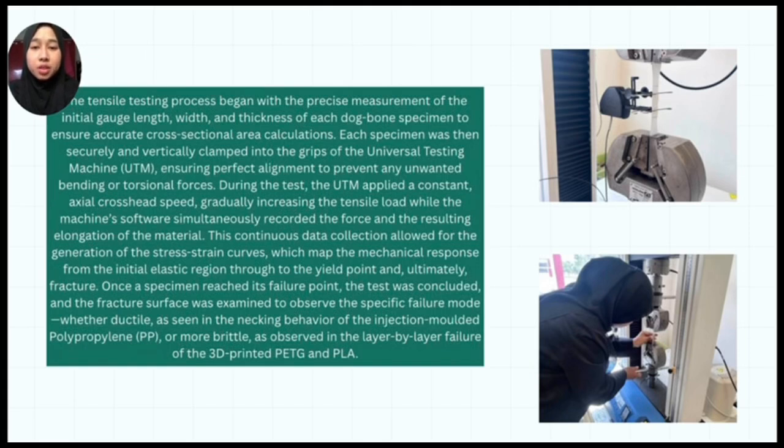Once a specimen reached its failure point, the test was concluded and the fracture surface was examined to observe the specific failure mode, whether ductile, as seen in the necking behavior of PP, or more brittle as observed in the layer-by-layer failure of the 3D printed PETG and PLA.